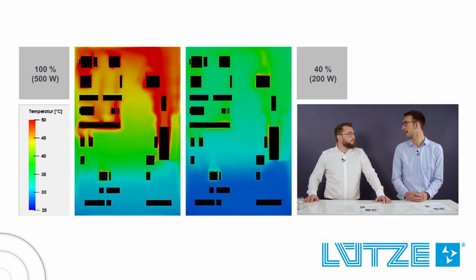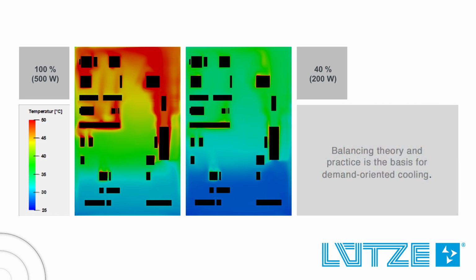So, out of the initial 500 watts we assumed, only 200 watts were actually inside the cabinet, which is a substantial difference. In this case, the calculation model wasn't flawed, it was the initial input data that was incorrect. Therefore, it's crucial to recognize that individual analysis is essential, not least because you never know how each component behaves during cabinet operation.